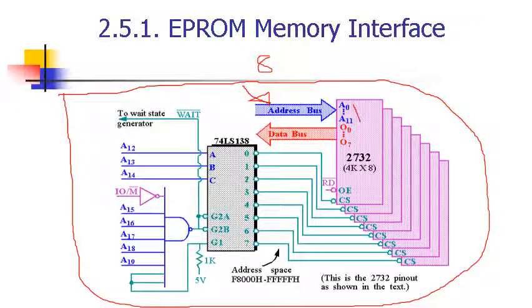From A19 to A15, remember, this is the required range of addresses, which tells you that the 4 most significant bits as well as the next most should all be ones, because you have here 8 and you have here F. So these 5 most significant bits should always be ones. 1, 2, 3, 4, and 5.